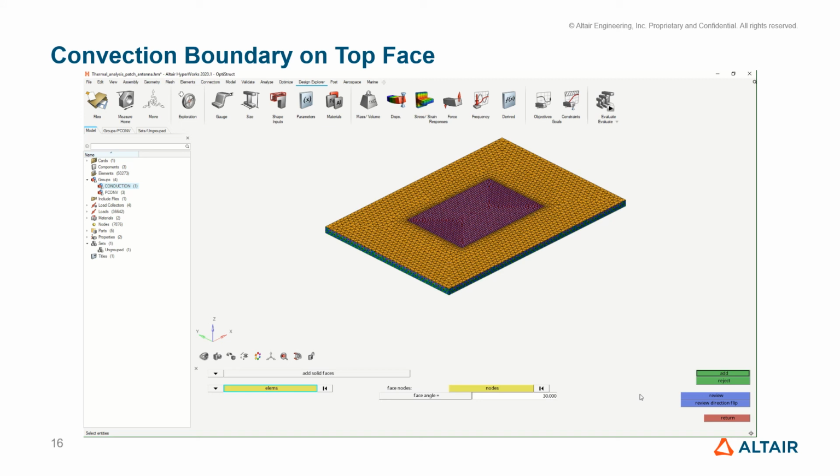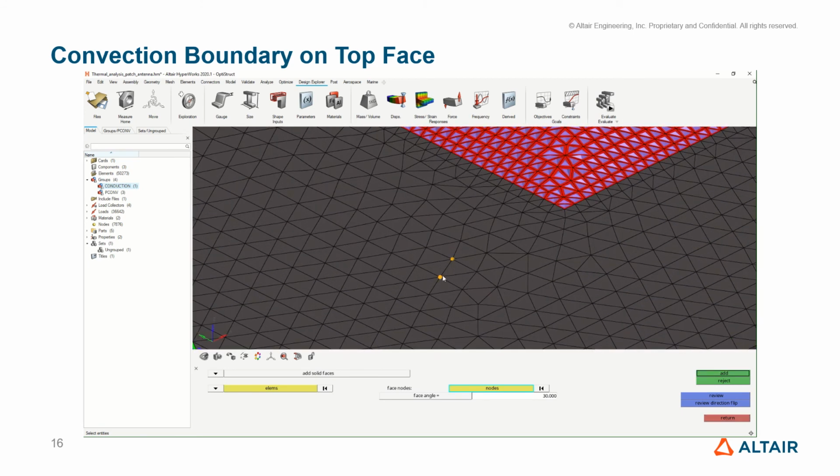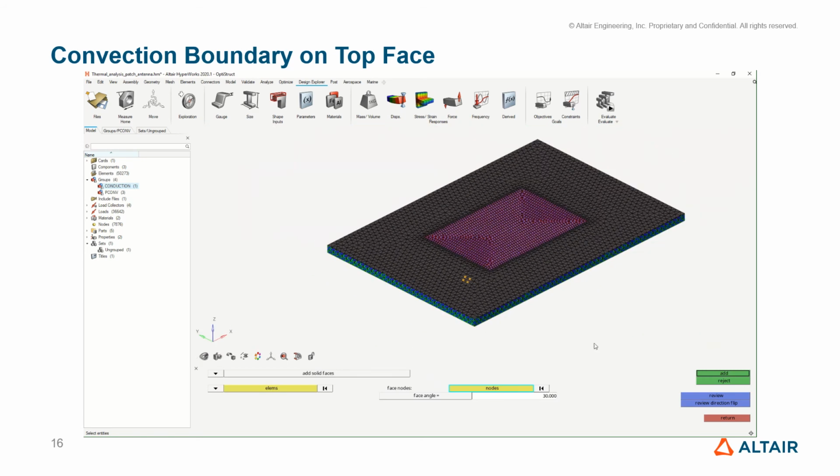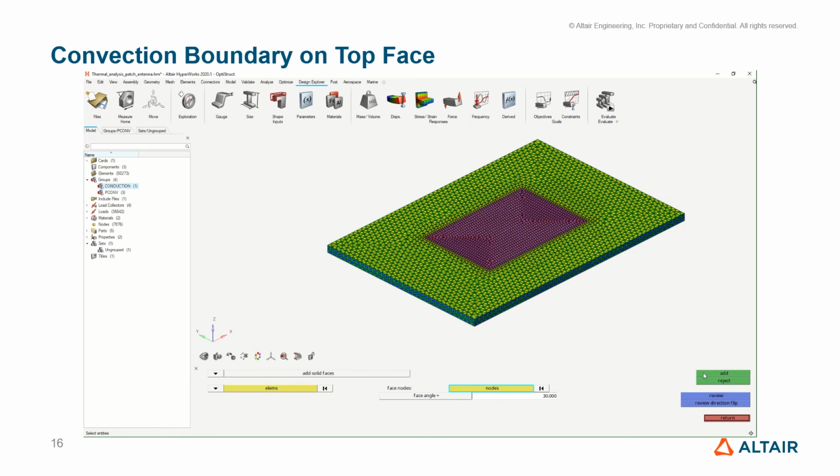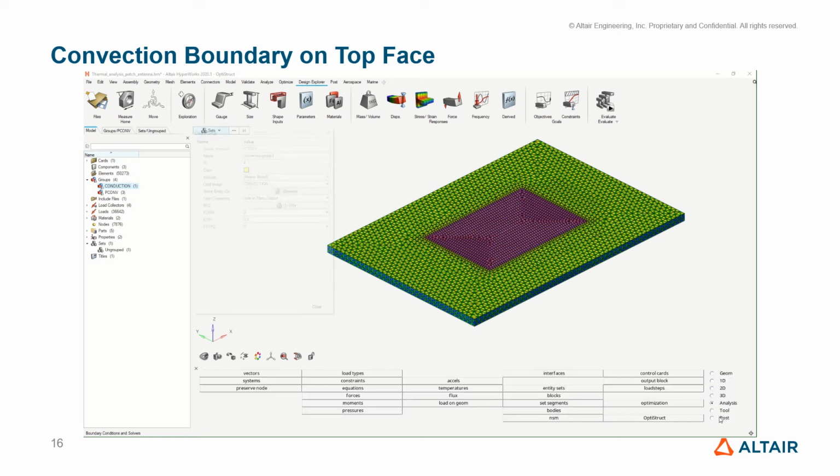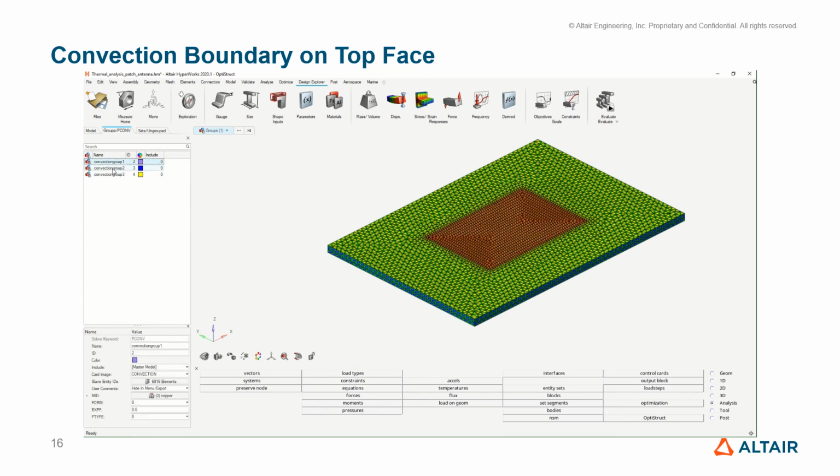Click the nodes in the yellow field and select graphically 4 nodes on the top surface. Click on Add. Click on Return. Then you should see a non-zero number in slave entity IDs. Click on Close to finally define the last convection group.